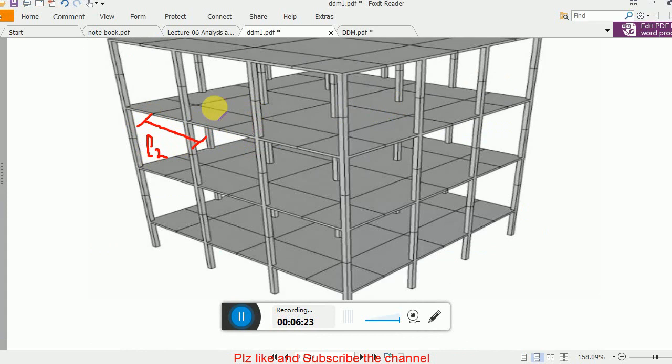This whole is basically in between these two continuous lines. This is interior frame in east west direction, and this L2 is how much? This panel length is 20 feet, 20 divided by 2 gives you this half distance, while in that direction also we have 20 feet, so 20 divided by 2 gives you that half distance. So L2 is nothing, it is 20 divided by 2 plus 20 divided by 2. I think it will be clear now.